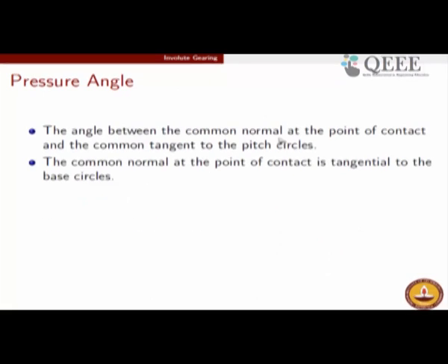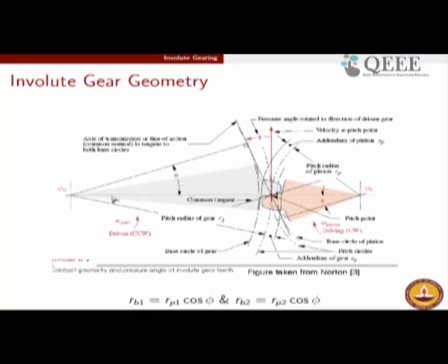The other component is going to simply go to the shaft, and it will cause a shaft deflection. So the other component is F sin phi. F cos phi is responsible for the torque, but F sin phi, the component which goes horizontally, is going to get transmitted to the shaft itself and cause a shaft deflection. So obviously, as we said in our discussion of the friction disk also, you would like to keep this component at the minimum. It so happens that the pressure angles used in general will be of the order of 20°, 22.5°, at the most 25°.